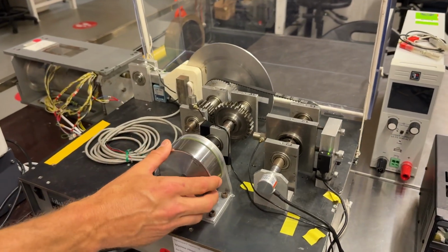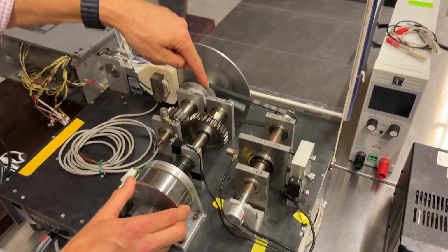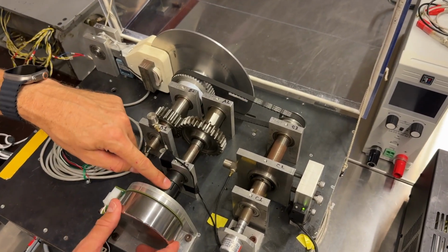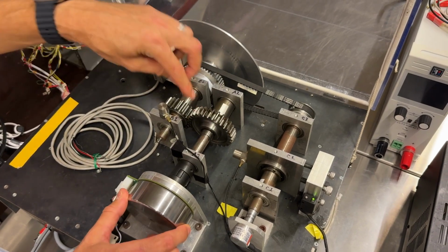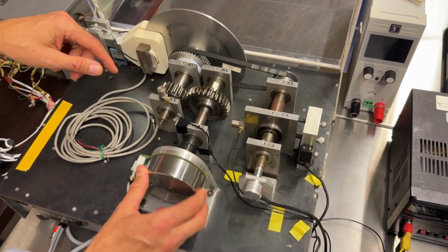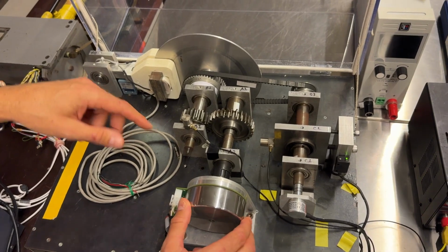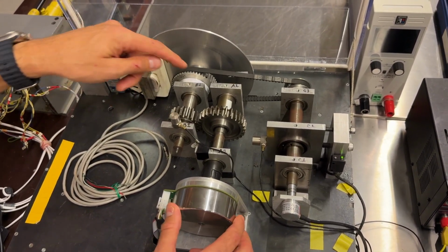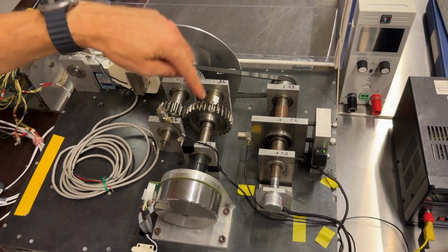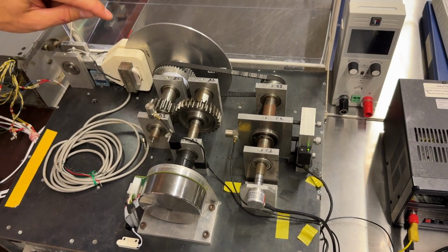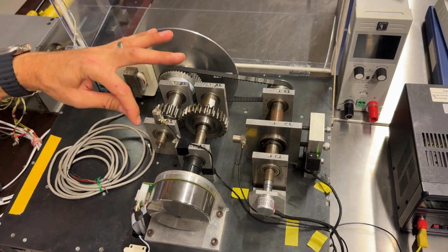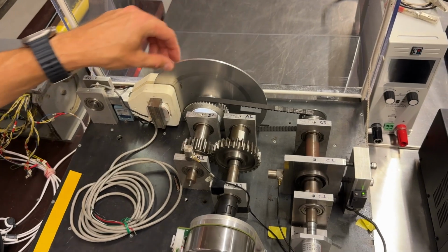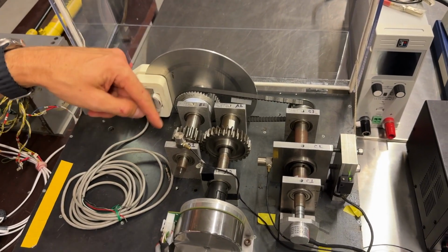So we have a rig here with a motor, a digital motor connected to a shaft with a gear on it with 29 teeth. There's a flexible coupling between the motor and the shaft, and these are straight cut gears, so as I rock this backwards and forwards you can hear there's some noise, there's some backlash between the gears. Obviously there needs to be some clearance in here, and these gears are in a ratio of 29 to 20 teeth, and then this driven shaft here is connected to an eddy current brake system, which we can use to apply some load to this driven shaft system.